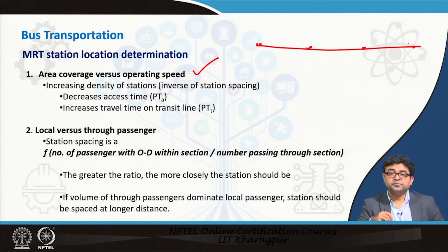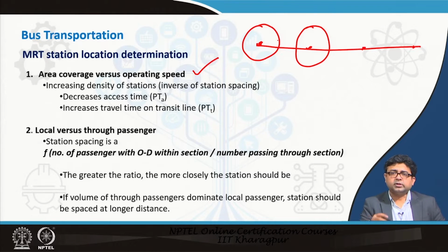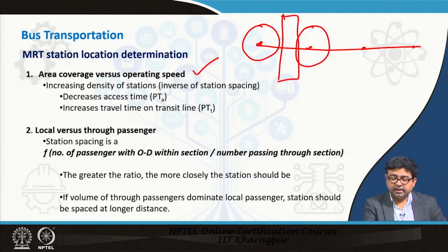and here. So, for example, this station location is going to cover, say for example, this much area, whereas this station location is going to cover this much area. That depends upon how dense the population is, do you have enough street network there, do you have enough feeder routes. So, all of those determine the coverage area of a transit line. So, in this case what is happening is now this much of an area is getting neglected, right.